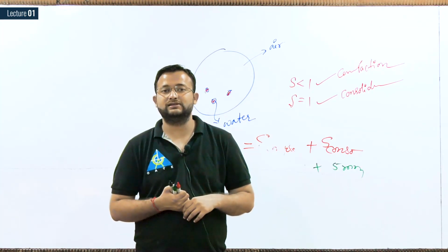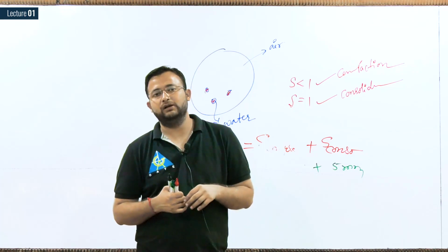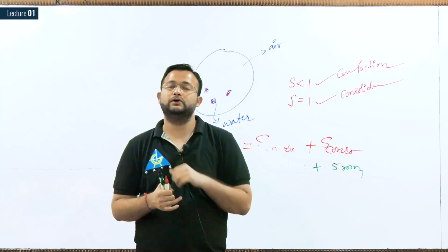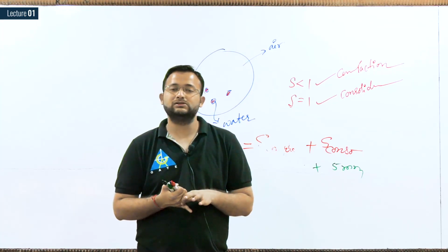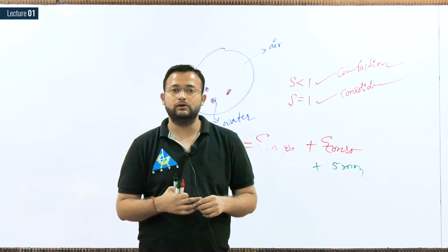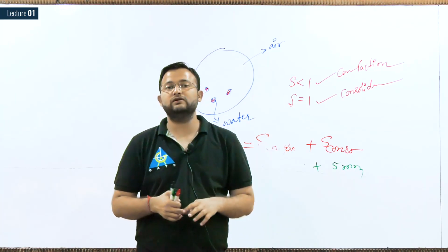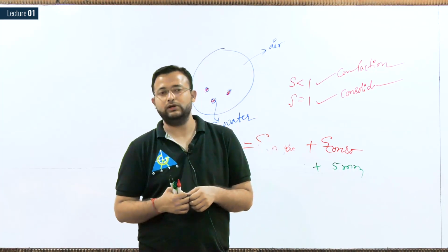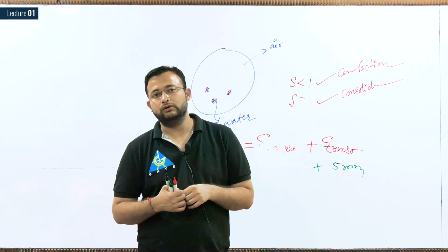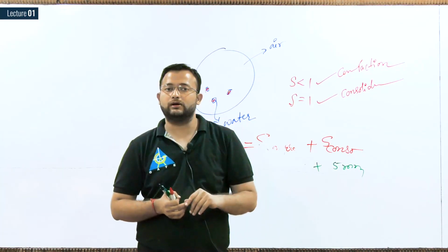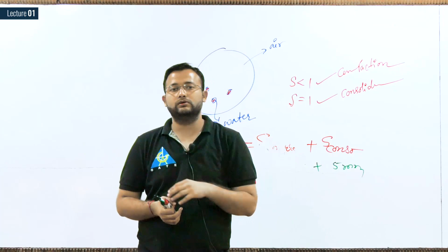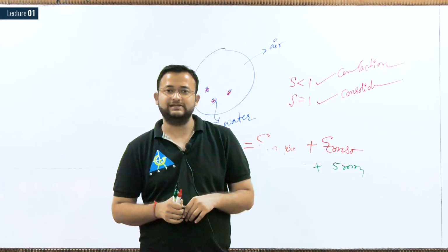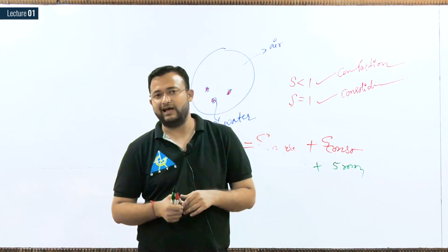But then also I suggest before the construction, you people should compact your soil, because when I visit a plot, I see the compaction of the plot, and I notice if I apply the load, definitely some settlement will occur, even though the soil is very stiff. Then also some amount of compaction will happen, some amount of settlement will happen.